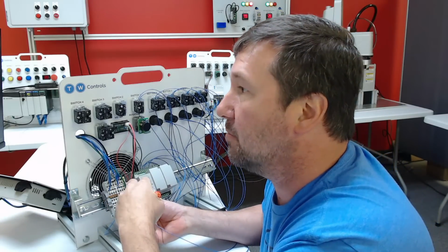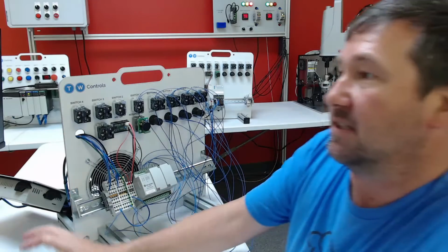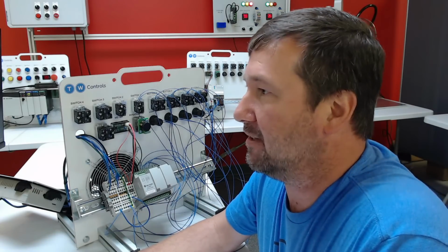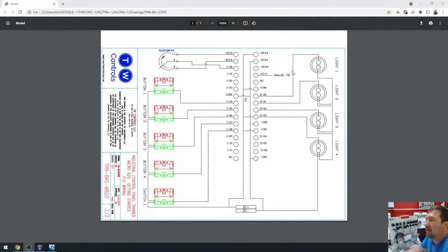Let's see. So it looks like the switches are sourcing to the PLC inputs. No, Rod, they are sinking. And so if we can, man, Rod, I should have had that link ready. I'm going to have to go dig a link out really fast. But no, the way to remember it is if it's sourcing, then you're going to send power out of the input, and then it's going to go to the 0 volt. In this case, we're taking power from the plus through one of our contacts and sinking it to the minus.